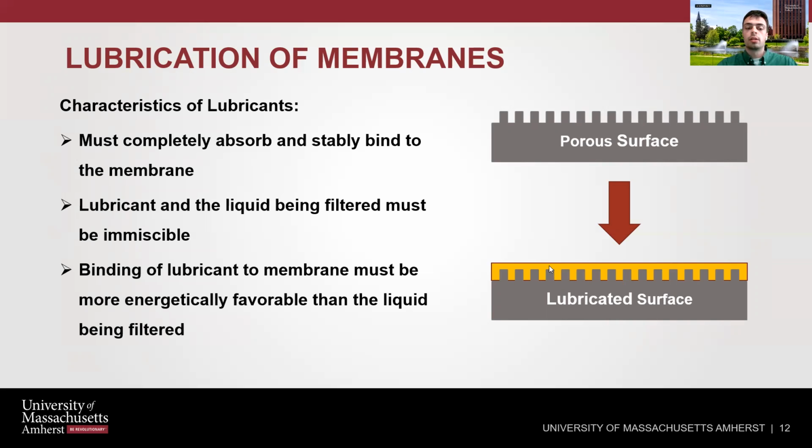The lubricant and the liquid being filtered must be immiscible so the lubricant stays pure on the membrane. And finally, the binding of the lubricant to the membrane must be more energetically favorable than the liquid being filtered binding to the membrane. So the lubricant isn't washed off the membrane and isn't lost at all. So it constantly stays there. With these characteristics, a membrane would gain many anti-fouling properties and increase its lifetime by a lot.